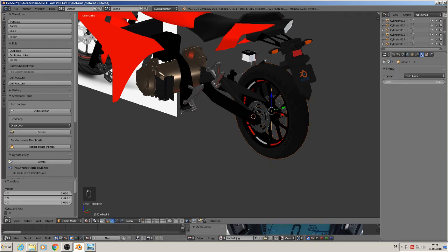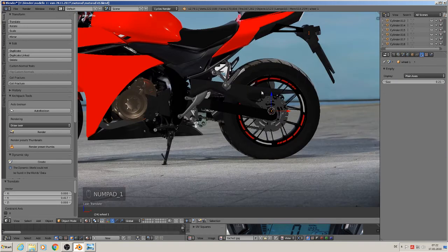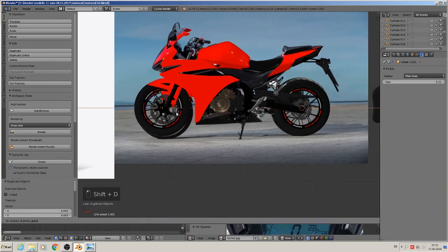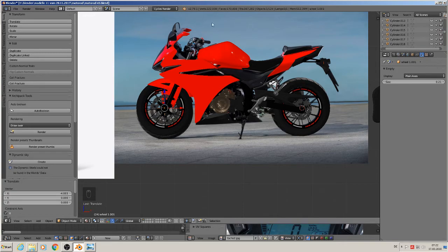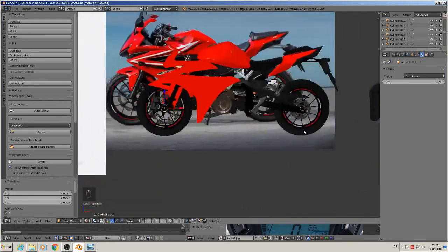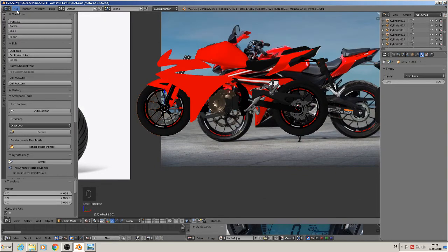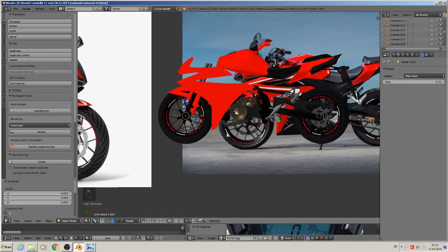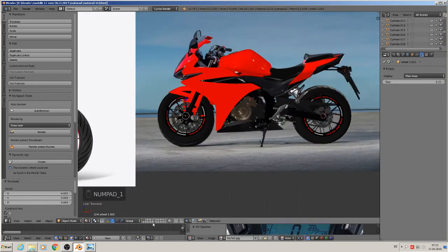So here you can make this cross smaller, and you can normally Shift D, copy that and all this other stuff, and you see we have a second one, and nothing appears here in the vertices, and that makes it faster to move and do the rest. Yeah, and that we have to do with all this stuff. All must go to this layer and must be an instance.